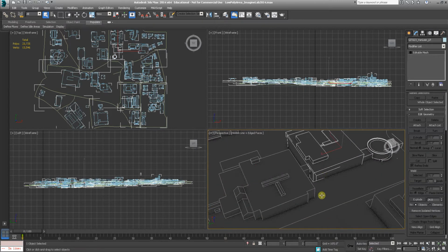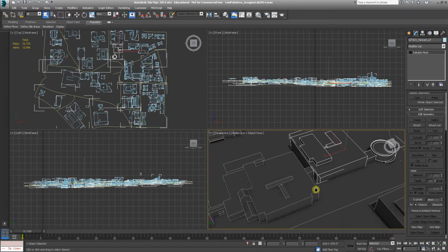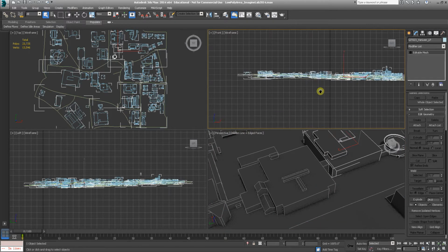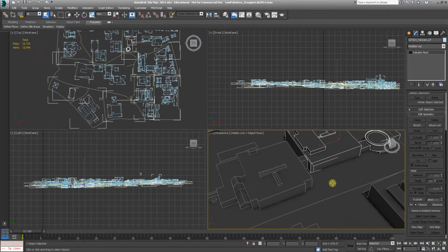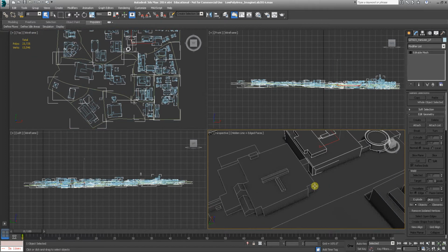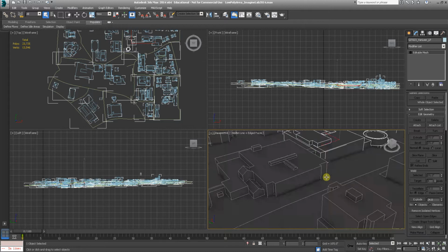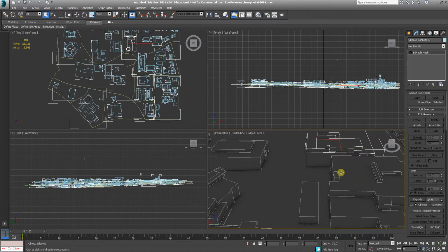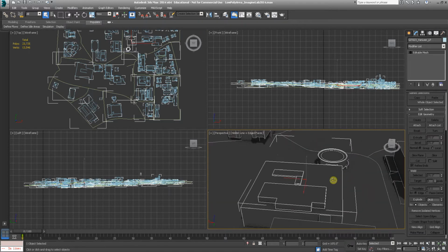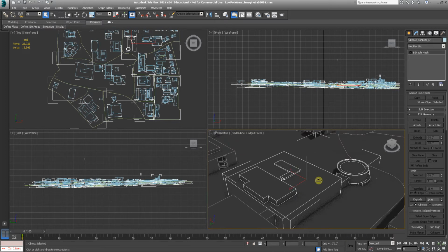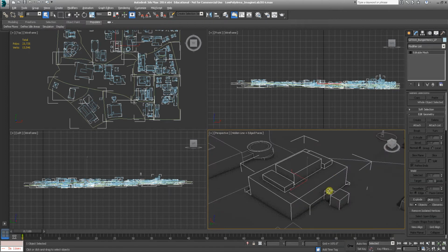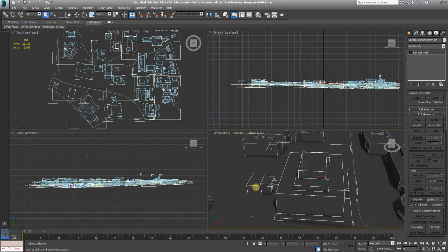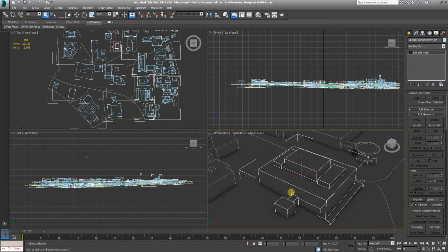So I'm just clicking on these, the basic movements. If you middle mouse click, it'll pan in the viewports. Just click down on the middle mouse and then move while you're holding it. If you hold the Alt key down and middle mouse and click and move, it will rotate. And if you hit Z, it'll select or zoom to a selected object. So you can roll the mouse and zoom out, select an object, hit Z, hold Alt down, which is right below it, middle mouse click, and view around the 3D model.